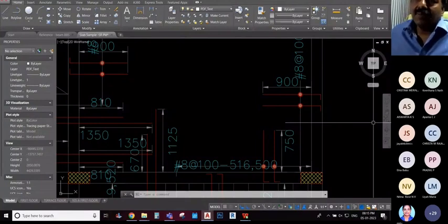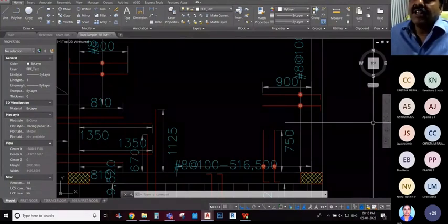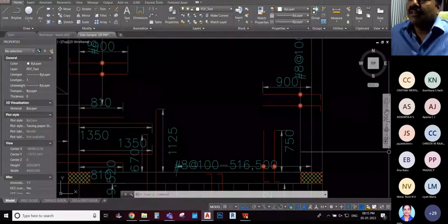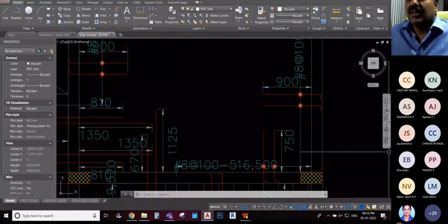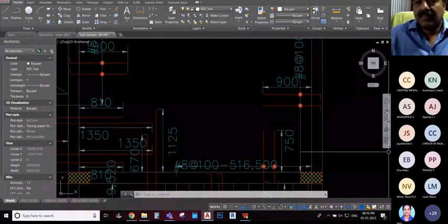Most of the time we see that people give it in schedules. They just group it as S1, S2, S3 like that, for 3-4 slabs, and they give just LX and LY long. They also follow this in the beam design and detailing. The problem is that many of the things cannot be very simple. There can be many reasons why we are giving it like this. We can play with all these possibilities. If we detail it accurately, we are actually detailing to save the reinforcement also.